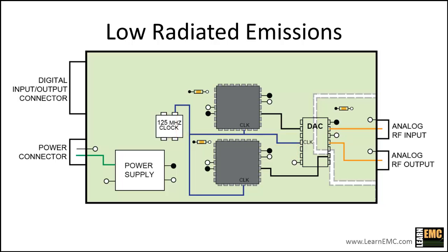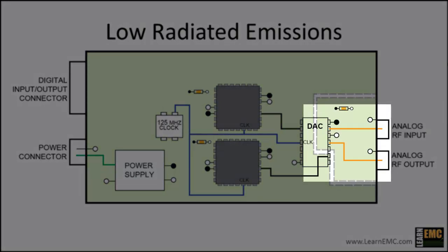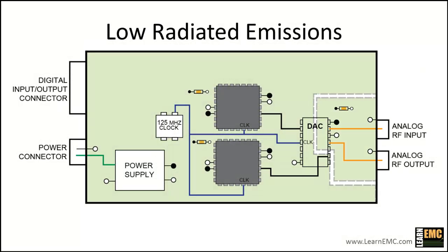If, for some reason, we were concerned about interference at frequencies below 10 kilohertz, we might want to provide an isolated return path for the analog signals. However, low-frequency coupling to RF circuits is usually not a major issue and can generally be addressed by controlling the bandwidth of the receiver. Even if we elected to isolate the return paths of the analog circuits, we would never do this by gapping the ground plane between two external connections on the board.